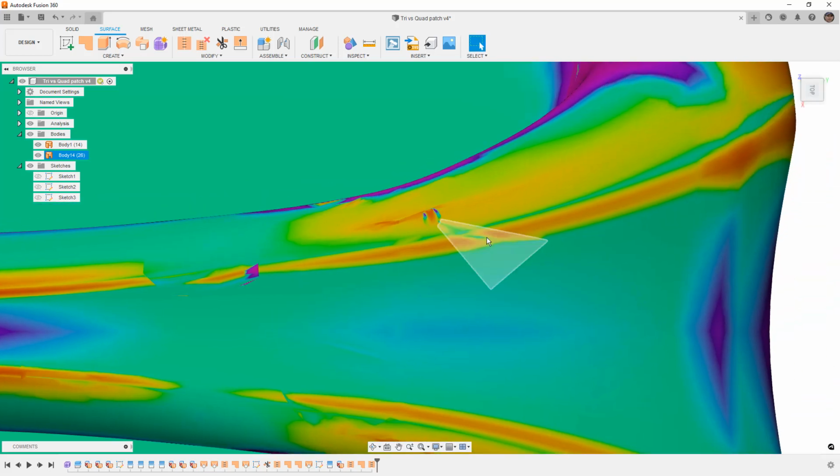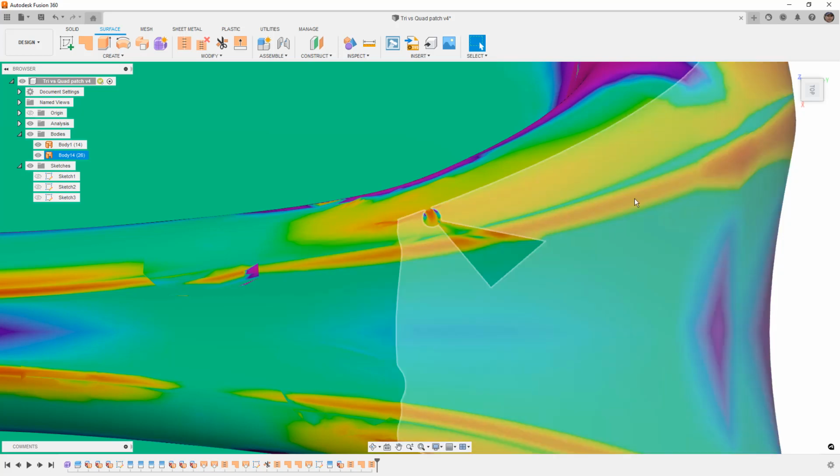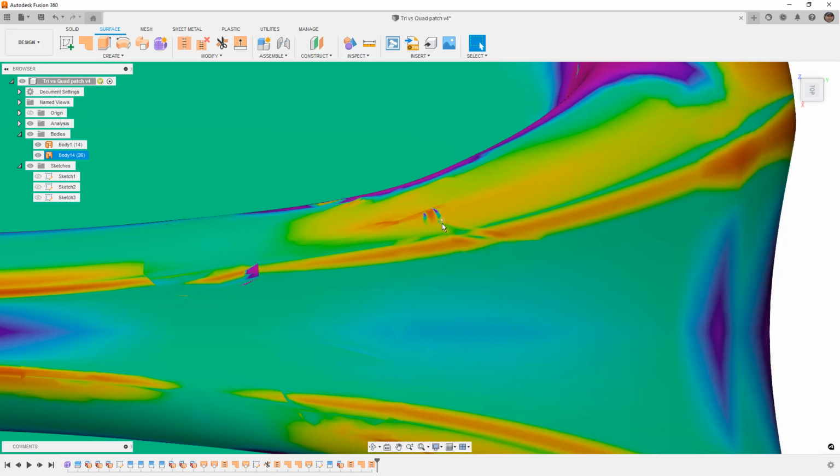The worst case was the triangular section. Now, the triangular section, the patch didn't work because that feature that we're trying to sort of carry through the design, it didn't work with the loft because it had that degenerative point. The loft was sort of bunching up in that corner, and that's universally true if you're lofting a triangle. If you're lofting a triangular opening, you are always going to get that degenerative point just by the way that the loft tool works in any CAD software that I've ever used.